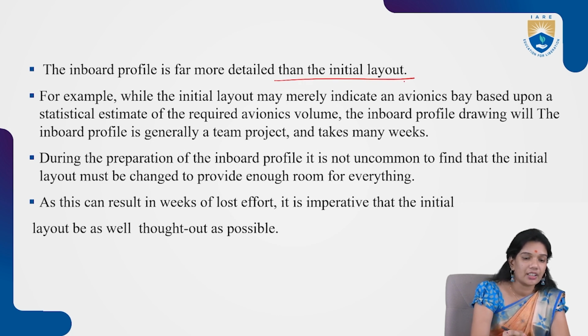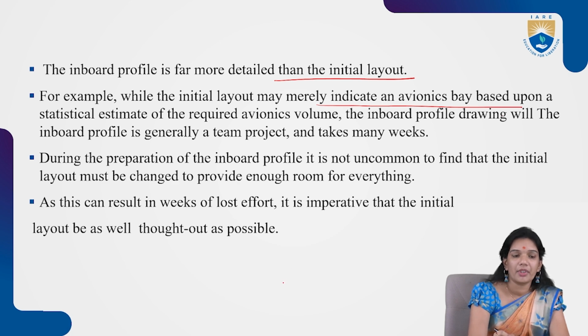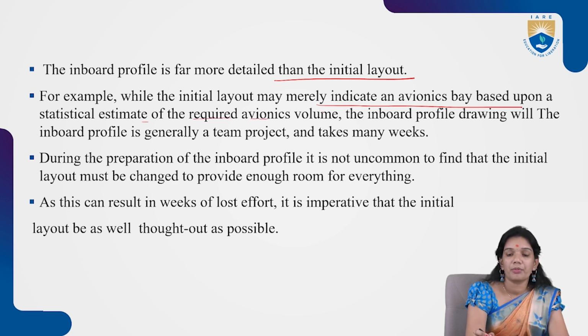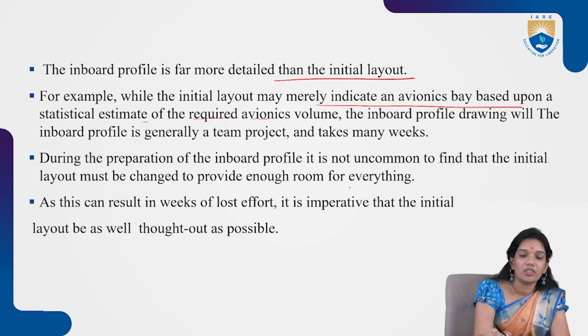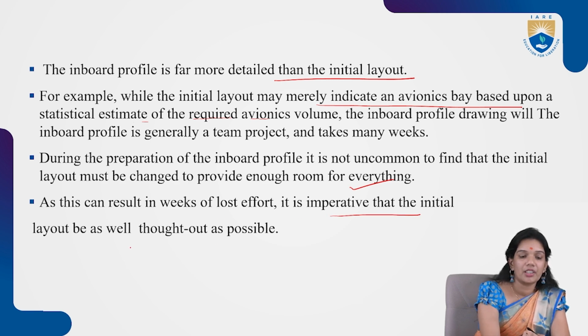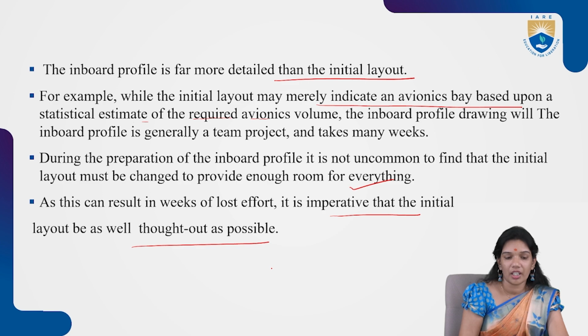An example is taken. While the initial layout may indicate an avionics bay based upon the statistical estimate of the required volume, the inboard profile drawing is generally a team project and takes many weeks, right? During the preparation of a profile, it is not uncommon to find that the layout must be changed to provide enough room for everything, right? So as a result, it is imperative that the initial layout be as well thought out as possible.